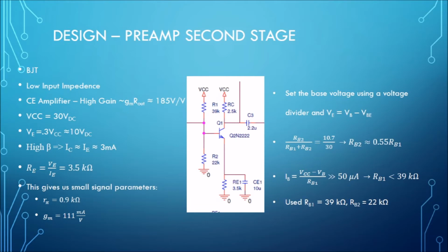volts of room between mid zero level AC signal and VCC, where it would saturate, and we wouldn't get any higher than that. So it's possible we could have chosen RC to be higher to give us more room. That's a consideration we make in the future.